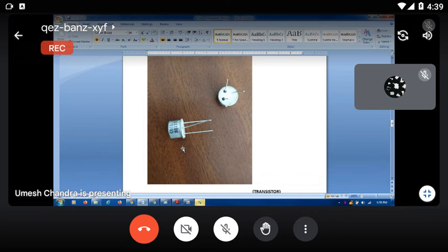If you don't have a multimeter, suppose, sir, without a multimeter, we cannot distinguish between NPN and PNP? Yes, sir. No, without a multimeter you can also identify whether it is NPN or PNP by just checking their value or number. Another procedure, I think, is by signals, because NPN switches on by high signals and PNP on low signals. Yes. So by switching on or off, we can also distinguish between NPN and PNP.